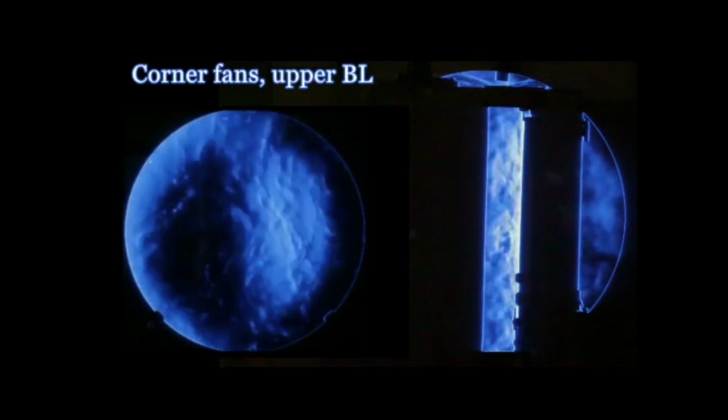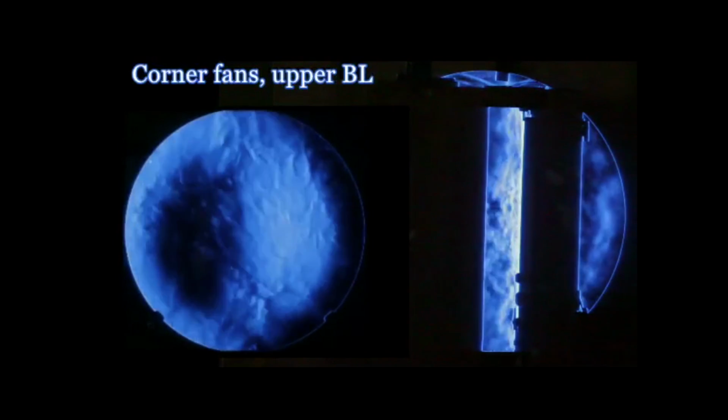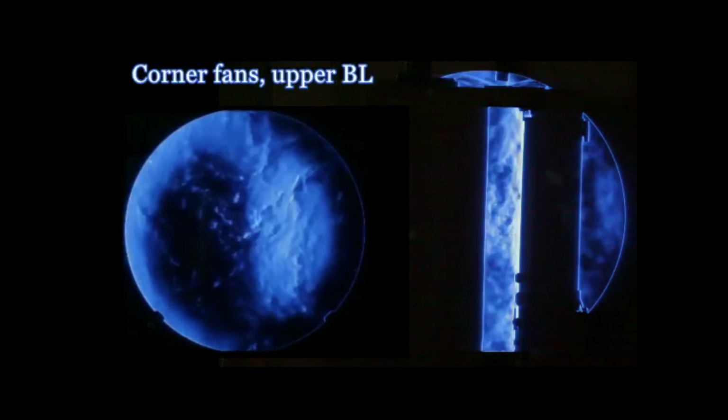Now, if you're only going to use it in one location and the weather is the same every day, you might be able to do that. But in most cases, you can't. So what I try to do is leave a tiny little bit of undercorrection, but not a large amount. I mean, I've had this problem with the 200-inch Hale that has this massive rim. They actually insulated it. So insulating the edge of a mirror can help get rid of this problem a little bit.